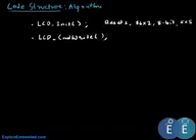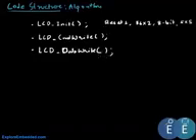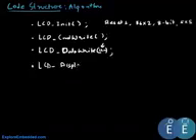So commands, as we discussed earlier: lcd display clear, display home, all the commands that we discussed earlier. To write a character on the lcd, we use the lcd data write function, and it takes a character as input and displays it on the lcd. Now there are various other functions like lcd display string. It basically uses the data write function and displays an entire string on the lcd.